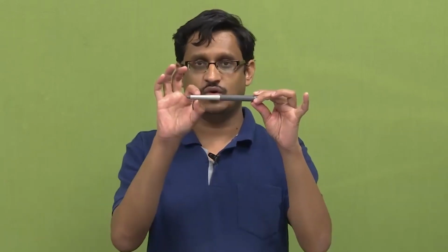Because there is going to be absorption. The optical fiber, if you remember the structure that I showed you in the first module, is something like this. It has a core, it has a cladding, then there are jackets, and all this is not some kind of hollow tube, they are actually solid materials. They are made out of fused silica, and you know that no material will be completely loss free.